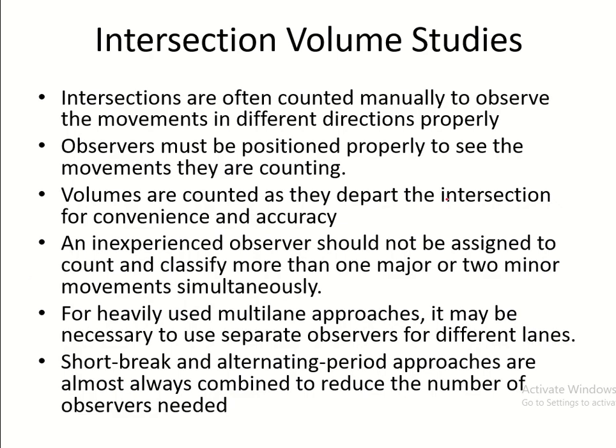Okay, now we come towards intersection volume studies. We have already discussed a little bit about volume studies which are done on segments previously as well. We have done some calculations as well. So let us focus on intersection volume studies, and we can move back to the segments as well, or we will discuss some advanced topics in volume studies. So intersections are counted manually most of the time.